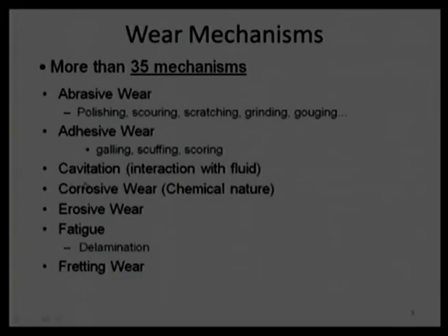When we talk about cavitation, basically we are talking about solid versus liquid. It is something like bubbles getting burst, and because of the bursting of the bubbles, there will be excessive pressure, which will directly impinge liquid with a high velocity on the surface, and that will cause some failure, which is known as a cavitation failure.